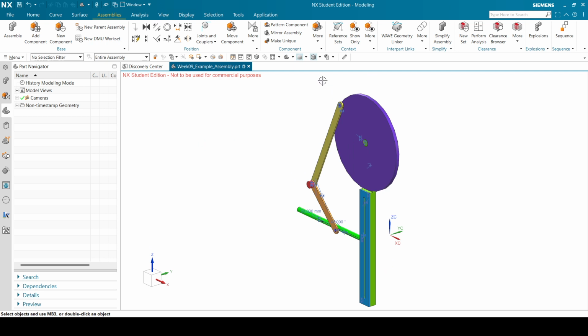But yeah, go around, play with stuff in NX, take this, try and build it differently. I didn't use all the constraints here. You can use them. For instance, you can use concentric. I've never had a situation where I had to use concentric. I know some other people use concentric instead of aligning center lines. I prefer aligning center lines.